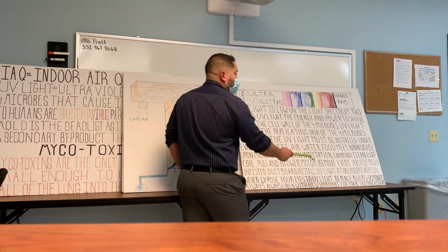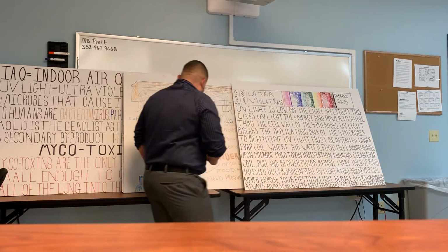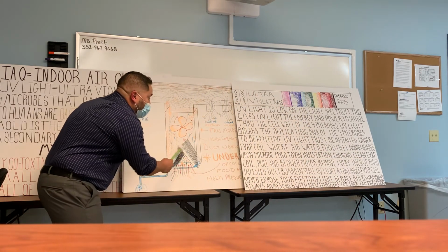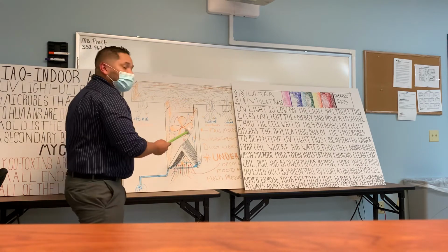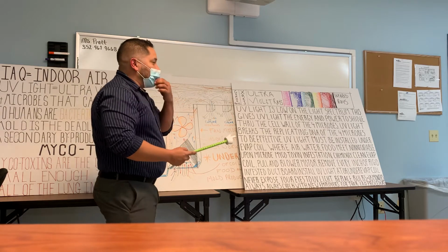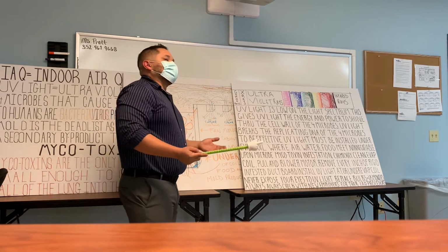First thing you want to do is chemically clean the evaporator coils. We can get up underneath there, or sometimes we have to pull the complete coil out. It's only a 3-year-old system. It's worth saving. If it was 8, 9, maybe 12 years old, maybe it's time to think of a replacement.